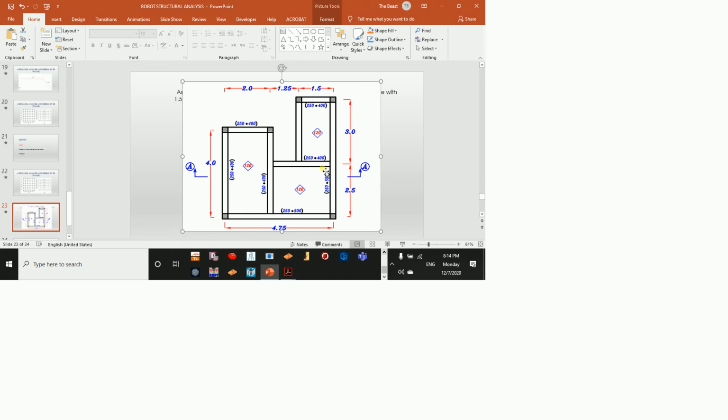In beams, always the cover is higher and the diameter is higher. In slabs it's less. For example, if you go for a slab, these are smooth slabs, so these are fine. That's why they are having a slab of, for example, 4 by 7. It's not a one-way slab, it's a two-way slab. You always design for the shorter span.